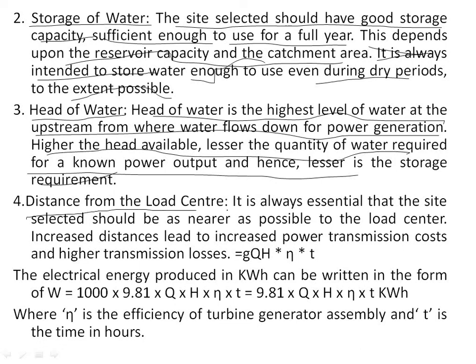Fourth one, distance from the load center. It is always essential that the site selected should be as near as possible to the load center. Increased distance leads to increased power transmission cost and higher transmission losses. So we need the load center as near as possible to the power station.